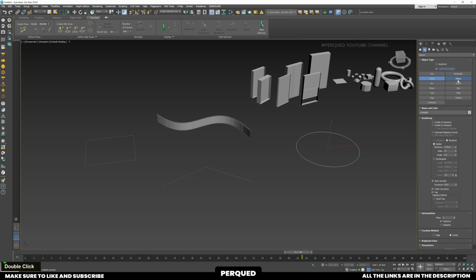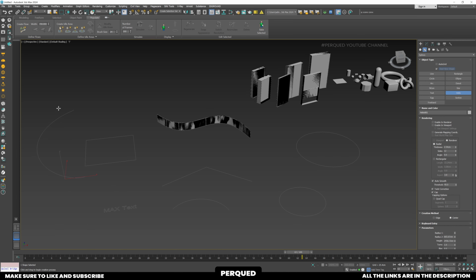Now let's first create some other shapes, and we are going to look at their properties. Let's create rectangle, circle, ellipse, arc, text, and freehand. Freehand basically works like drawing on a plane, so use it carefully. Now, when you select each spline and go to the Modify tab, you'll see their properties. When we go to the Modify section, I'll talk about these properties in detail. Right now, just test out length and width and some basic parameters from your end.